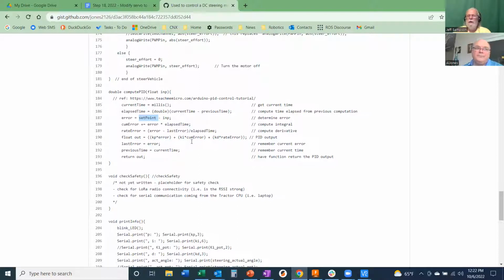Okay. Technically that angle is in radians, but I convert mine to degrees just because I don't think in radians. But regardless, it's an angle. It's just a scale factor between those two. Cool. So that's why I was saying if you convert your target pot into an angle, then you can use the angle directly. Or if ROS hands you something as an angle, you can use that directly. Either way would work on that.